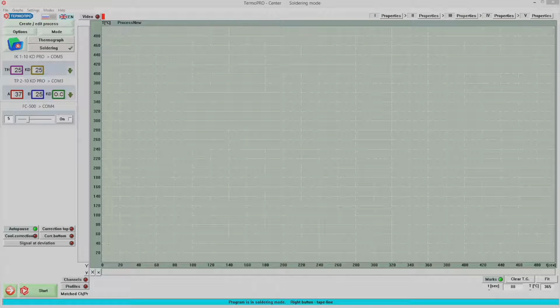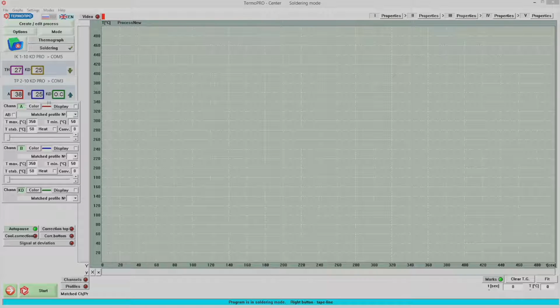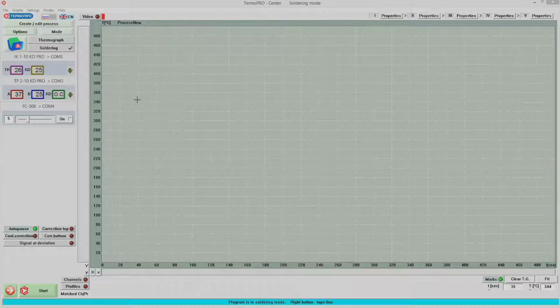When the NP3424AB Pro bottom heater is used, a function that helps to synchronize its two heating plates is available. This option is helpful when operation turns from small to big boards. Changes in this function are made by setting a check mark in the bottom heater panel menu.